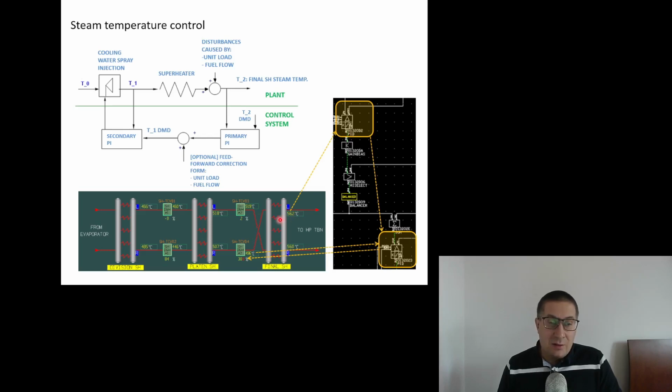And you remember my last video about the fact that in the DCS system you don't only see the values, but also the quality of the measurement. Here is such a case. You can see the valve is open to 30%, but the DCS system does not trust this value. That is why it adds the bad quality indicator.